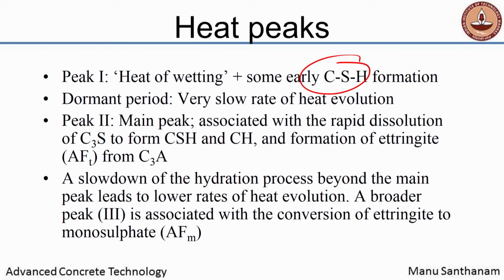Okay. But heat of wetting is a phenomenon that most powders will exhibit even if they are not reactive. The idea is that each particle of the powder is a solid and it has got some surface active atoms, right. So, when you cover this particle with water, you form a new bond between the surface and water. The surface atoms have a very high energy. So, now this new bond that is forming is taking some of that energy, but what about the balance energy? It is going to be released as heat. That is called the heat of wetting. It is because of the surface active atoms which are forming a new bond with the water releasing the extra energy that is left as heat, and this will happen with any powder whether it is reactive or not.